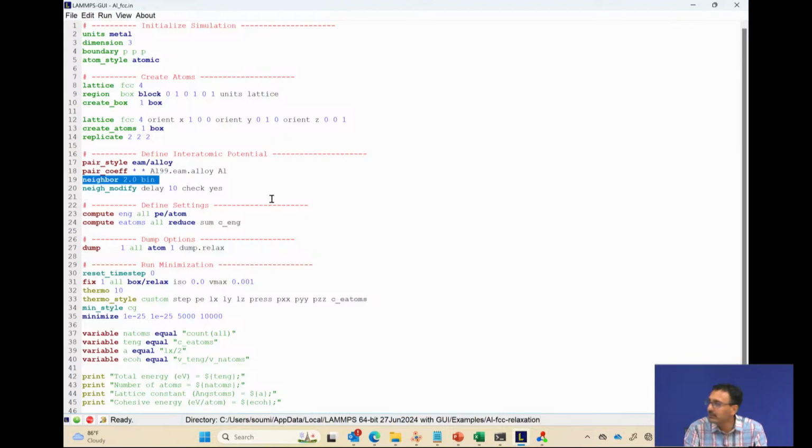The next step, yeah. Is the code smart enough that if you told it to do BCC aluminum, that as you calculated it, it would switch to FCC? It depends. The code will rely on the force field that specifies the interaction. So let's say incorrectly you used a different force field for iron, and on the other hand the mass and everything else you have is set up as aluminum.